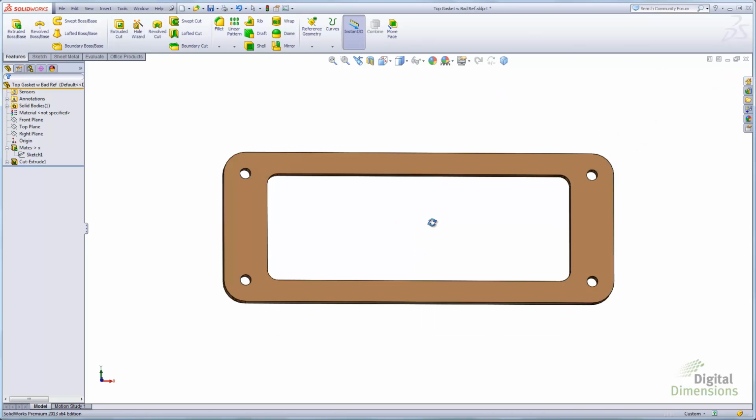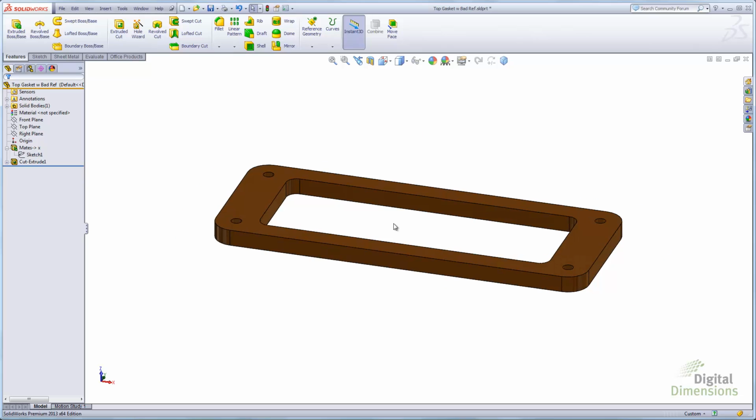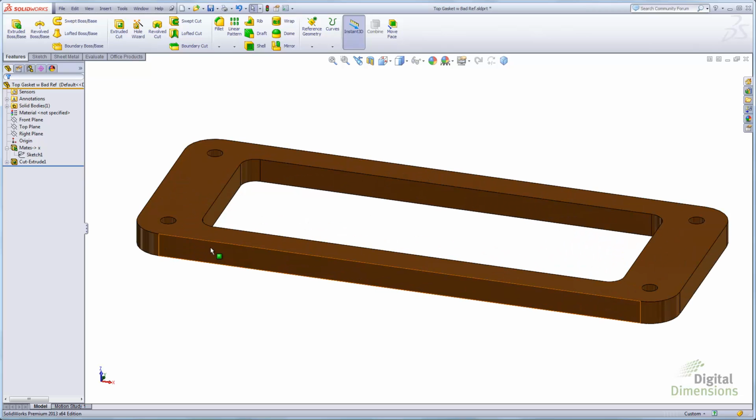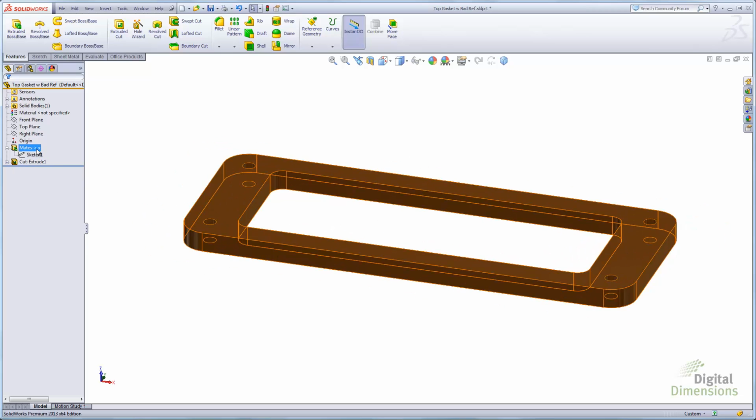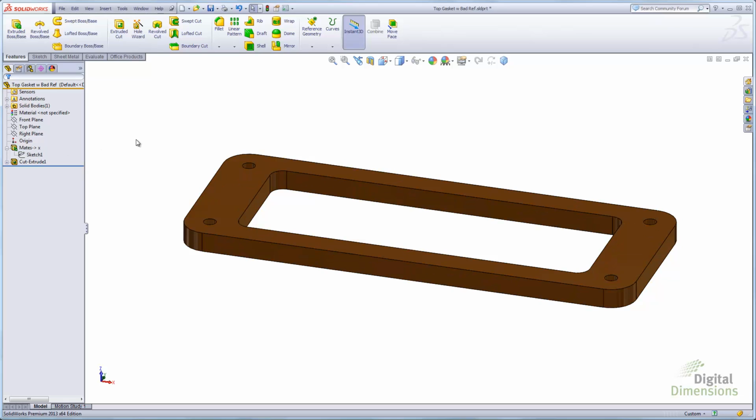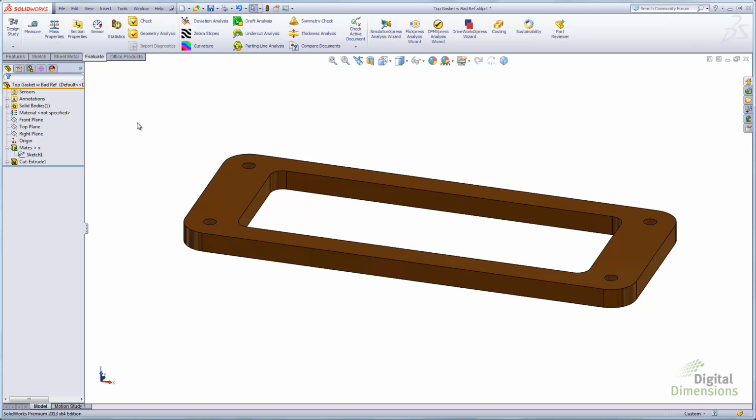Now the last step, and I set this up on purpose because this is a gotcha, is the thickness. So I fixed the sketch, but I still have an external reference here at the feature level. So why is that? Because someone might have used an up to surface or offset from surface. In this case, an up to surface was used to create that final external reference here. So a face on the assembly was used to create it.